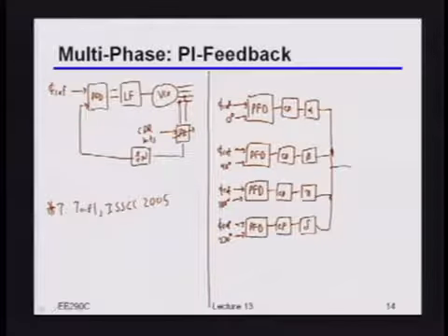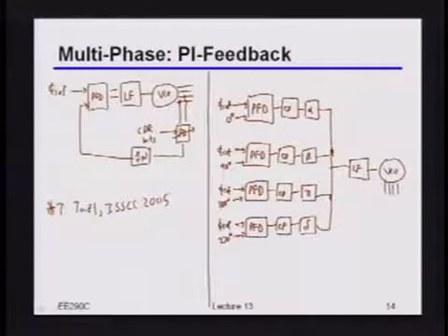Right, and of course I feed this through my loop filter, and then into the VCO, which then of course generates those 4 phases, right? Well, now by changing those coefficients, I can have the same effect as doing that phase interpolation, right?